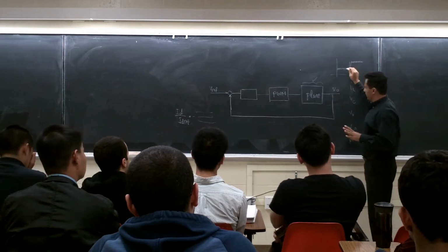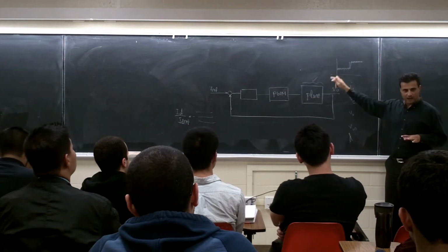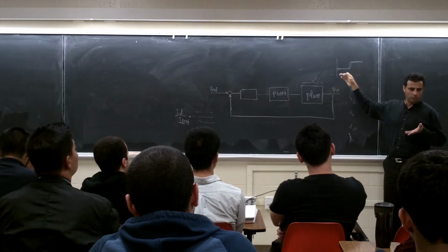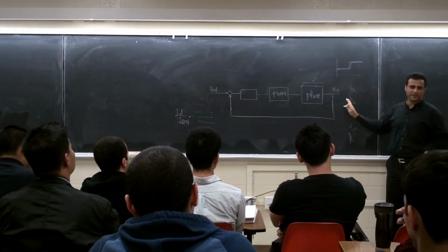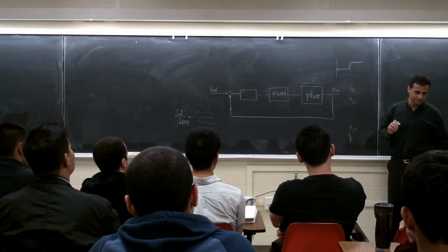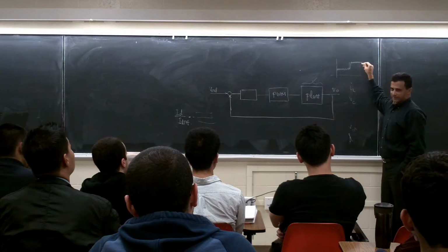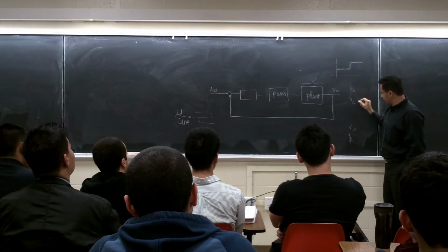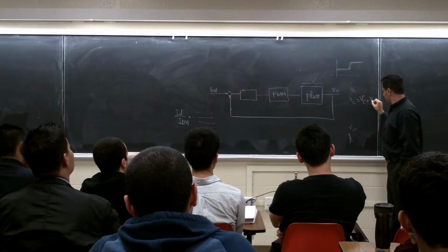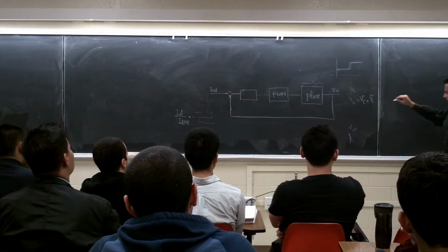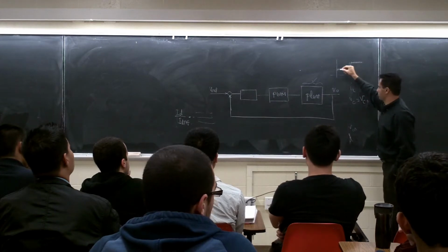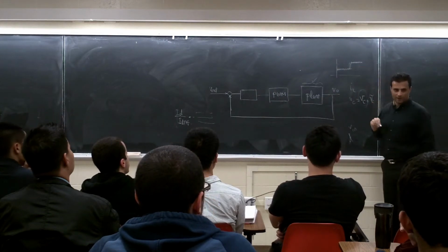For example, in the buck or boost converter we did, VO was VC, right? So I cannot put this one as an independent parameter. We have a VC, right? So this is a VC. I can say this VC is equal to capital VC plus VC tilde. So this capital VC is a DC operating point, is this value, right?